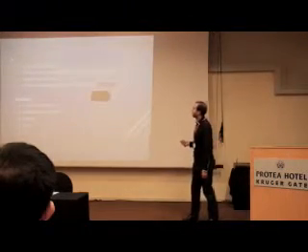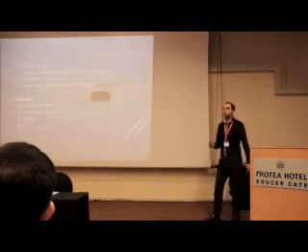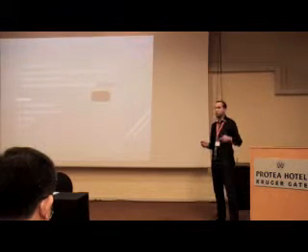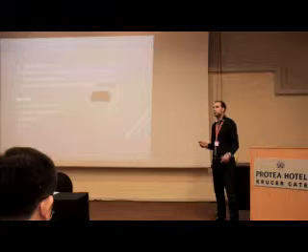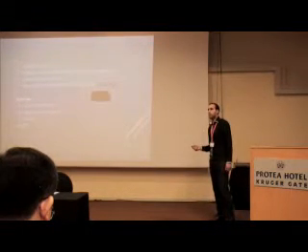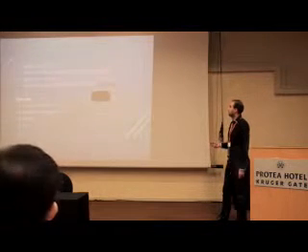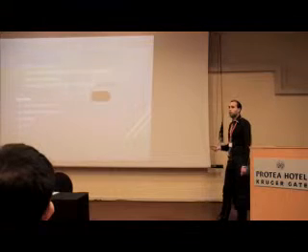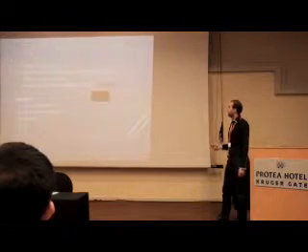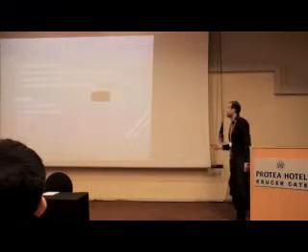So now, this is the progress. I have analyzed the bitstream using Vivado software. I have VHDL and Verilog files on the FPGA. I have done the digital to analog conversion, and I have done a BPSK modulation using two things. The first one is GNU Radio, which allows you to make a very simple modulation. For that, I just need one transmission and one reception USRP, which is there.